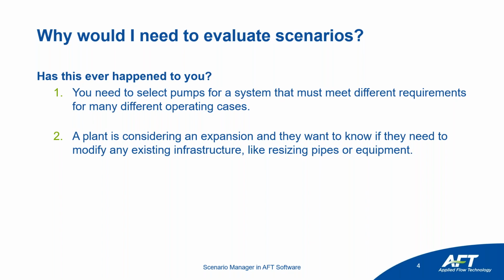If the expansion works out, if our pumps were oversized to begin with enough to justify that, that could be okay. Or as you get further into the design, you might build out additional scenarios. What if I resize these pipes? What if I replace this pump? What if I do both of those things at the same time? So again, the majority of the system would stay the same, but we can isolate and vary and tweak those minor changes in our unique scenarios.